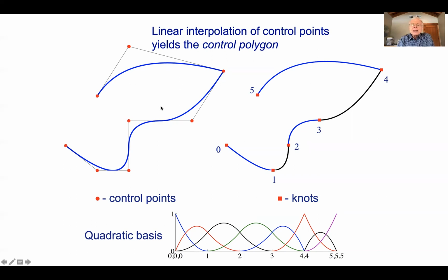And what it is, it's really the deconstruction of the computational geometry data structure into a finite element data structure. And that is facilitated by so-called Bézier extraction. So you break it up into elements, and you can build this entity with polynomials.